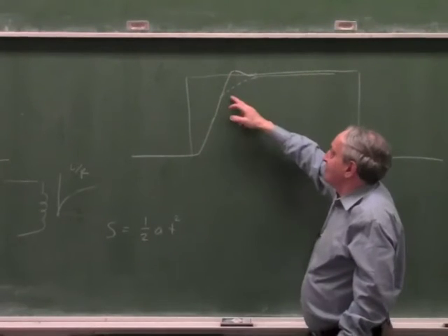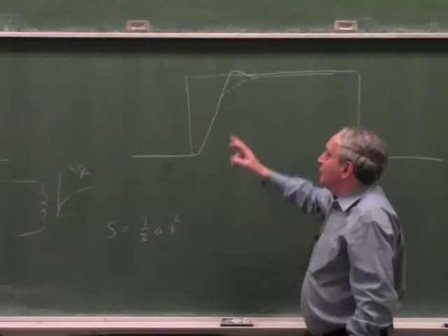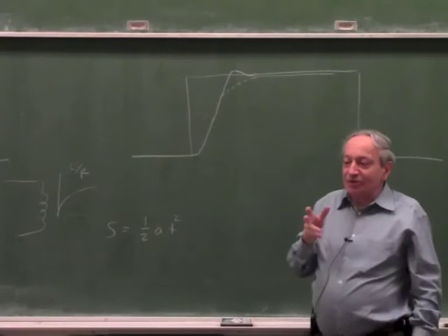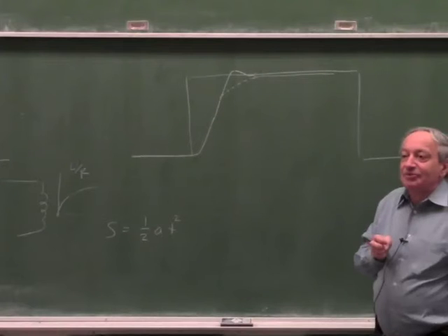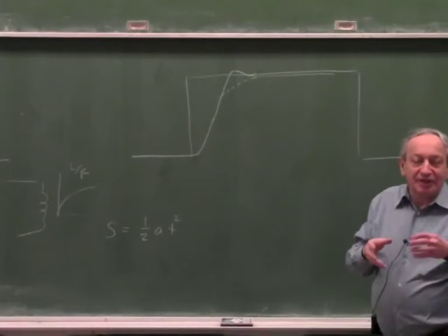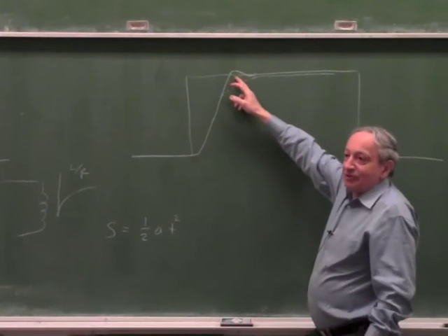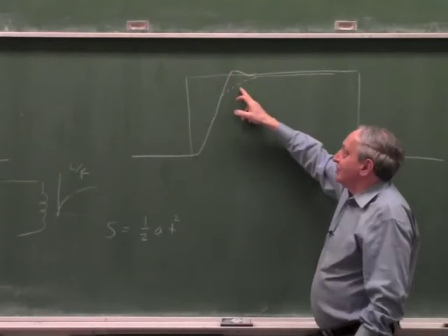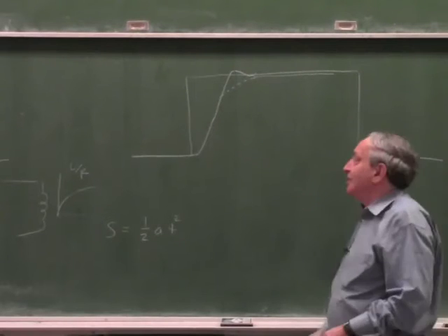See, if you did this, you never know, maybe it didn't have enough force to push to the target. So which response you choose has a lot to do with the use of the servo. Another example, if you do something in an oven, and it's temperature controlled, and you do something very critical in the oven, you certainly don't want an overshoot, because it can overheat. You'd rather wait a bit longer and do this. So the exact response depends on the application.